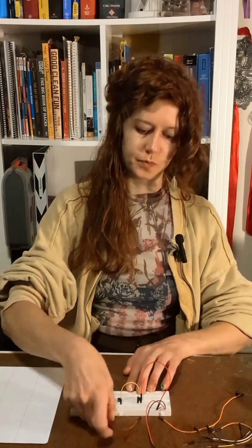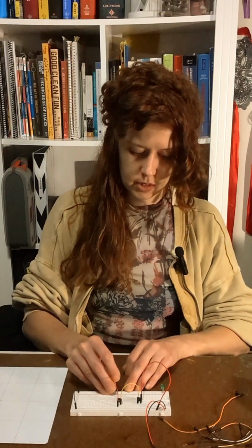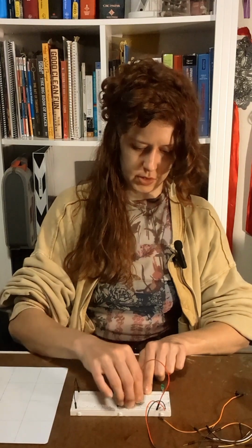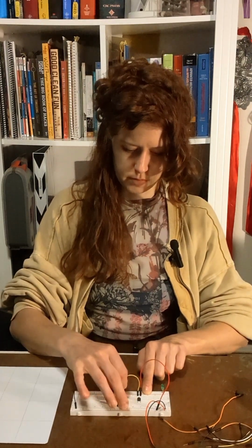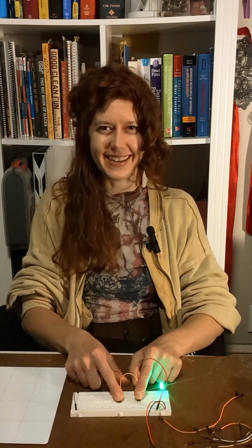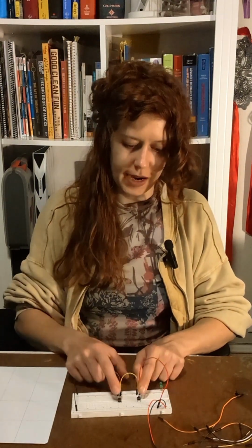Okay, so this means that we have to force the electricity to go through both push buttons to turn the light on. So, for example, actually I feel like I should move these so you can see this a little better. We'll flip them to the other side. There we go. All right, so if I press one button, nada. If I press the other button, nada. But ready? Dun dun dun. I wired this correctly. Haha, there we go. Yay, button. So an AND gate, both inputs have to be on for the output to be on.